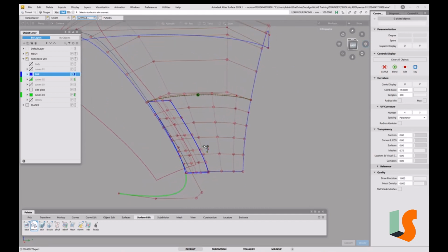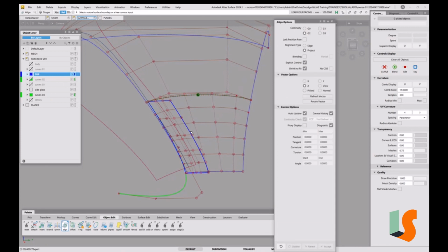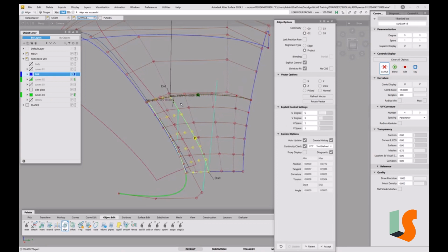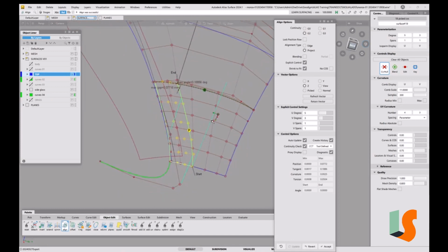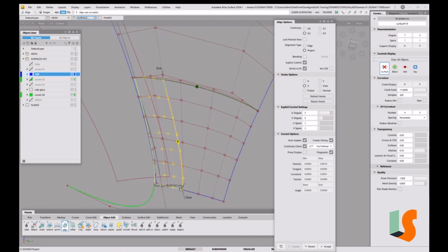And then we can just. Obviously, we did that in the top view, so you could see what's happening. I'm going to leave it at this point. But I'm just going to see what happens if we say line G2 project Z this into that. So I've got Z on and all of that. So we've not quite position matched there, and that'll be because we've got too low a degree. So if we increase the degree up to 7, we might get there. If we don't quite, it's actually not far off, 0.00143, which is nothing.